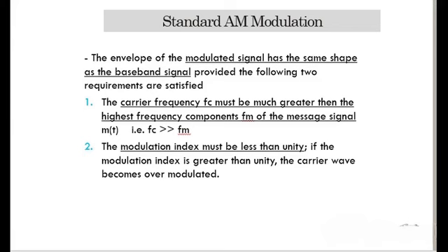The perfect modulation standard of amplitude modulation: the value of the modulation index should be 1, which implies the percentage of modulation should be 100%. For instance, if the modulation index is less than that, say 0.5, then the modulated output would look like the following. It is called under modulation.